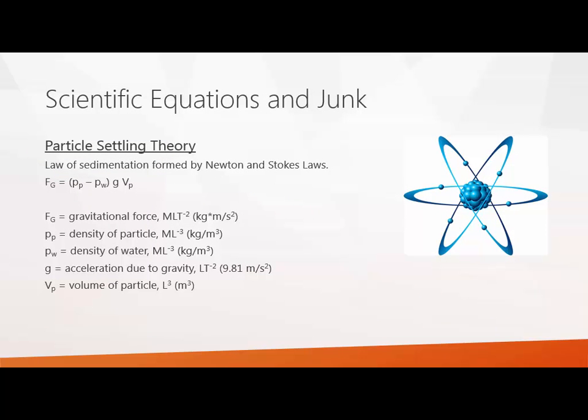I didn't really want to go into the equations because this is more of an overview. In 10 minutes, it's a little tough to go into details. But you have your equation, the law of sedimentation. It's formed by Newton and Stokes' law. That's the background. So you have your gravitational force, which is what's going to be pulling it down. Then you'll have the density of your particles, the density of your water, and acceleration due to gravity. I put it in metric for you there. And then the volume. It's a pretty basic equation.